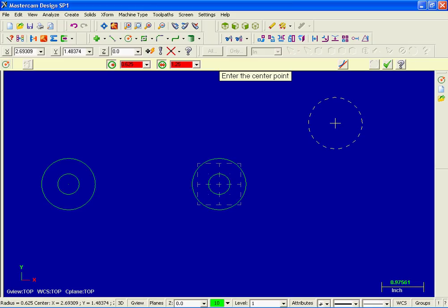The next thing I'm going to do is create the 1/2 inch radius circle up on the top. So let's go up, and in the radius section I'm going to click on this icon to deactivate the locking feature, and in the white space for radius I'm going to input 1/2 and then hit enter, 0.5.